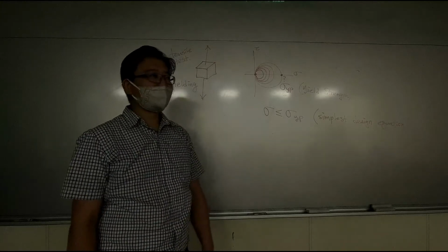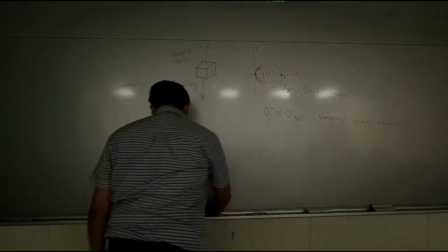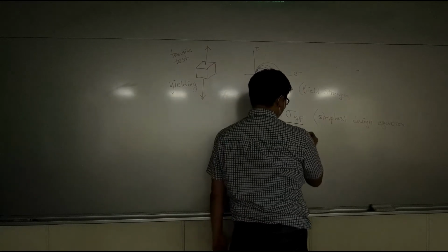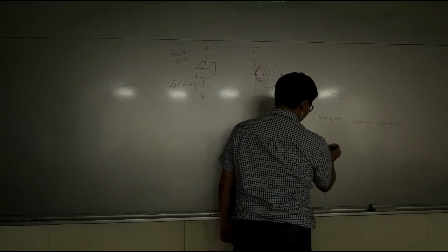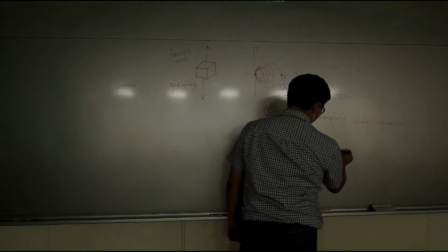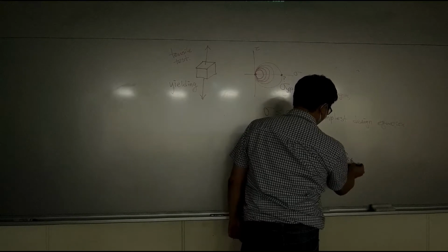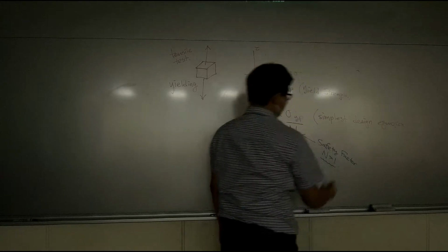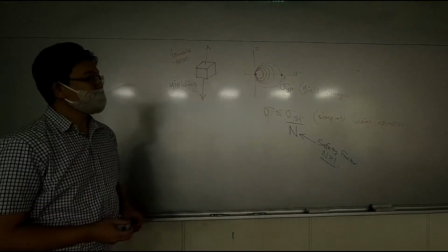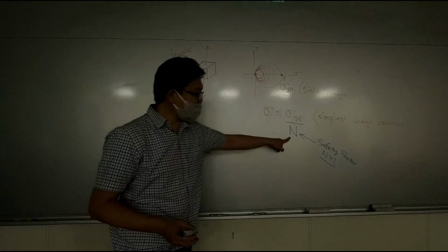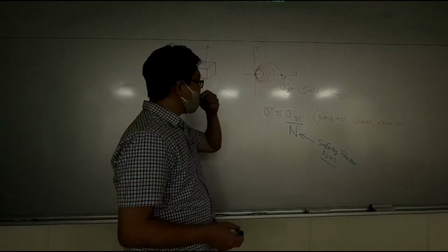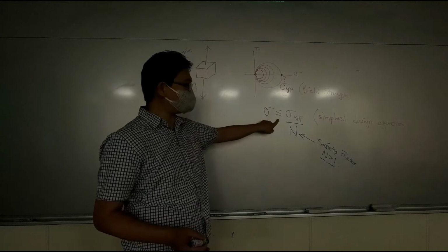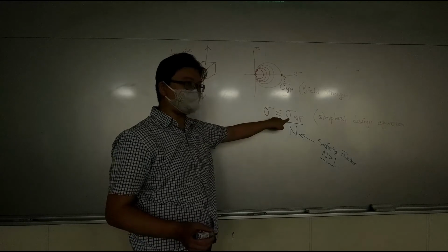But, like what we introduced earlier, we should put a safety factor right here. And usually, n is larger than 1. Because if we don't have this, we may have stress exactly the same as the yielding strength.